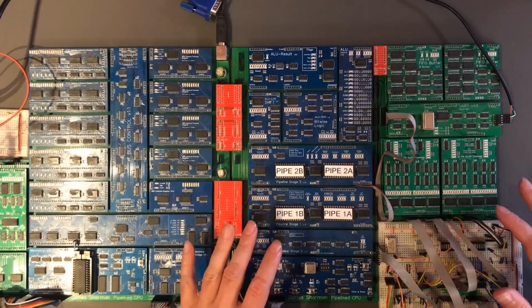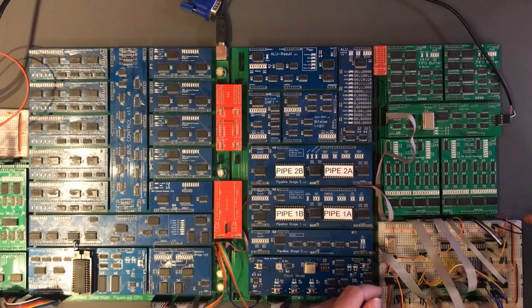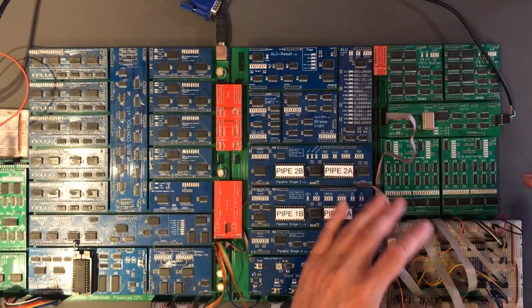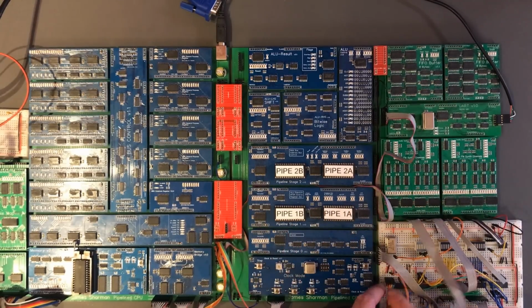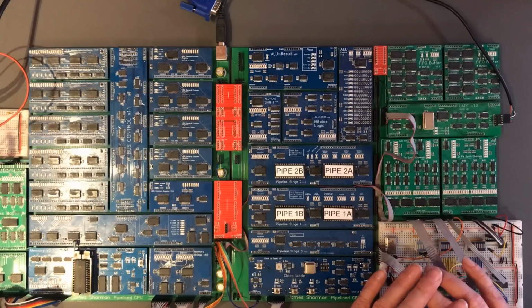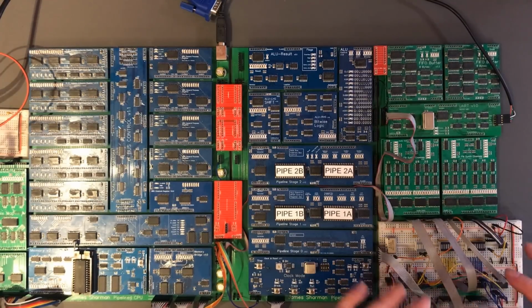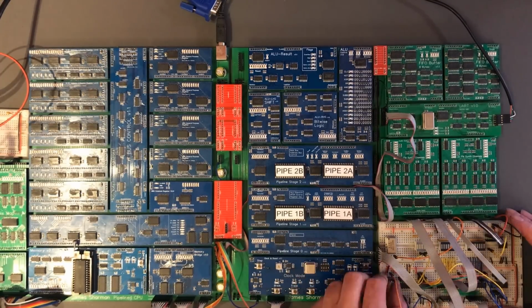Okay, so here's the main build. Now here we've got the audio circuit, and I think I'm going to move this out just to make room for those breadboards. There's also a specific reason for that. The I/O port that we use for the audio circuit, we only use the write port for it, and that read port is unused. So we're actually going to stick the controller onto the same port as the audio. Only one's write only and one's read only.